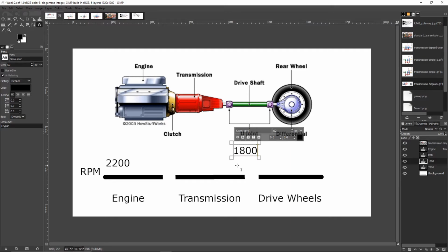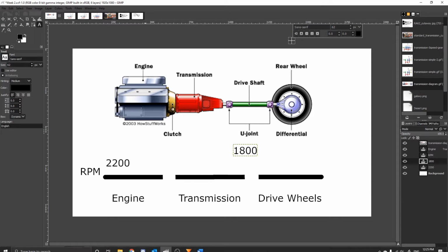Don't confuse overdrive with torque converter lockup, which we will talk about next chapter, next month, next module. In some vehicles, namely pickup trucks, there might be a button that says overdrive on and off. There might be a tow haul button on the gear selector. That's not actually overdrive, that's torque converter lockup. I don't want you guys to get confused, but overdrive is very simple. Anytime the output is overdriven, driving faster than the input, that's an overdrive situation.